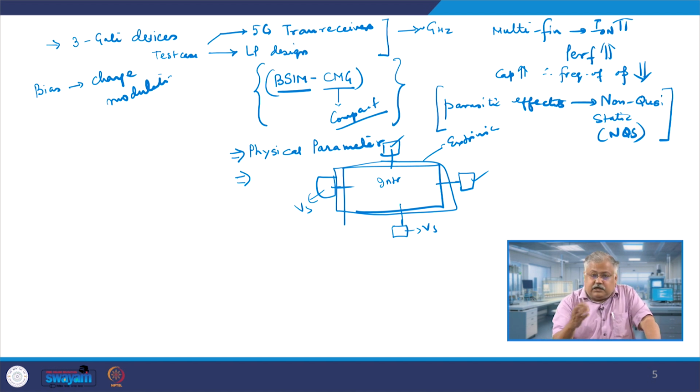Now, as I discussed with you earlier, and you must be aware of by this time, these charges are basically geometry dependent. So typically, if the two fins are very close to each other, how does it influence? If they're relatively far from each other, how the fins are placed with respect to source and drain pad, these influence the total capacitive model or the total charge collection model for the device itself.